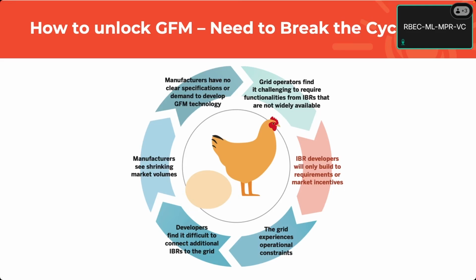What's happening in the small signal space, if you think of the control, we're going to talk a lot about control stability this afternoon, but if you turn up the gain on a controller a bunch, it eventually goes unstable in the small signal space, right? Not the big stuff, but it'll start to grow. That gets solved with a grid forming converter. So even in a weak grid situation, you're adding that stability back in even without the current headroom.